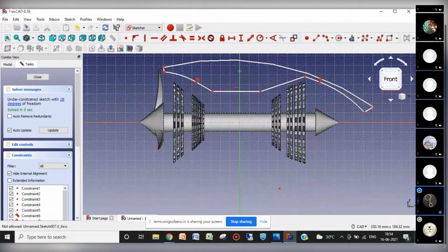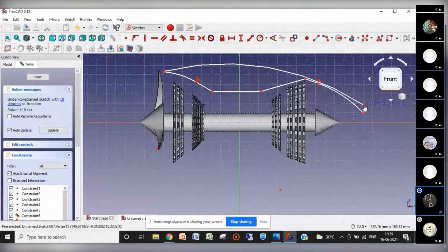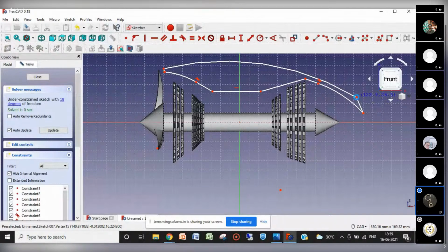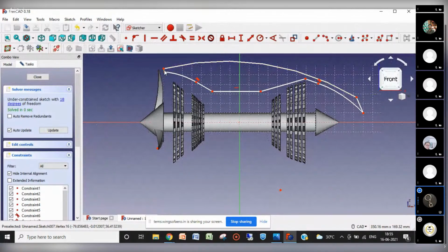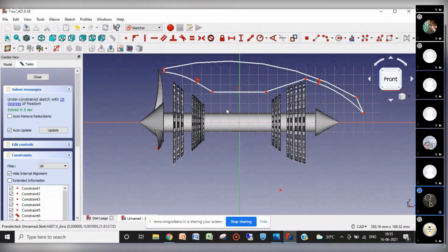Here, at this place, our fuel line and igniter would be placed. And this is not hollow as it is looking. Again, some holes are also there at this end for the bypass air, for cooling of the hot gases near the nozzle. And here we have our opening for the bypass air. Also note that afterburners, which add some fire ignition in the nozzle, are only in jet engines, not here. And thus this straightened part has the area for the combustion.